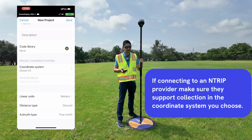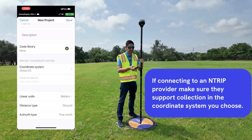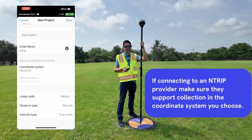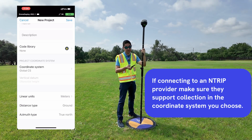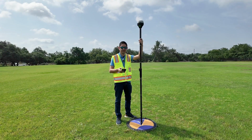In this case, we're using a provider that is using WGS84, so I'm going to try to match their settings, even the vertical datum, to whatever they're using, because it's very important that this, considered the rover, is matching whatever the base is projecting. And then once we have that defined, we are going to start surveying.